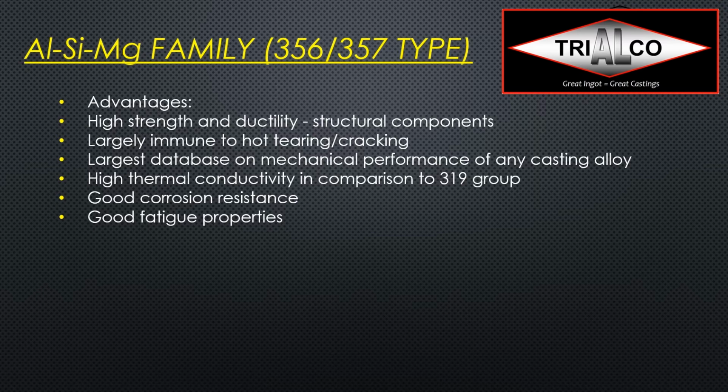We have largely immune to hot tearing and cracking alloys. We have the largest database on mechanical performance, mechanical properties of any casting alloy family. Pretty high thermal conductivity in comparison to, let's say, a 319 or a 380. Good corrosion resistance and pretty good fatigue properties.